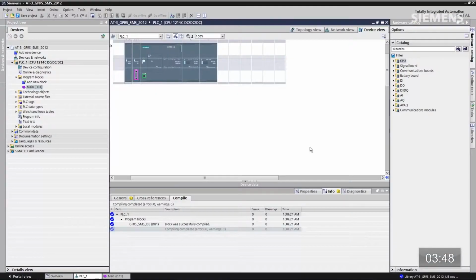So let's choose libraries. We actually have the ability to take tags, data blocks, function blocks. In fact, hardware configurations, you can test it, prove it, make certain that it's going to work for your application. And at that point, you can save the global library, reuse it over and over again. That way you create engineering efficiencies in your daily work. So let's do exactly that.